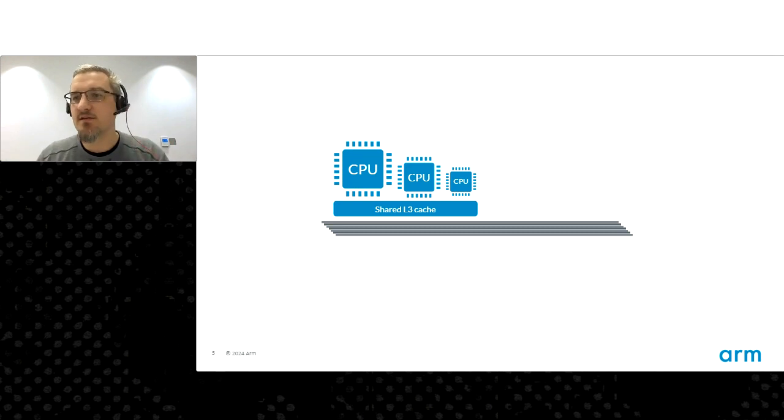The big cores give you the best single-threaded performance. And the OS can load balance where this workload ends up. Typically, you'll only have 1 or 2 of the very big cores, maybe 4 or 5 of the smaller cores. And this is purely because you can't power 8 big cores inside that power budget.